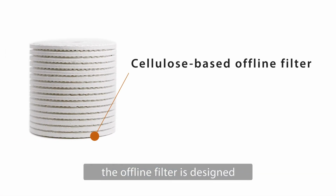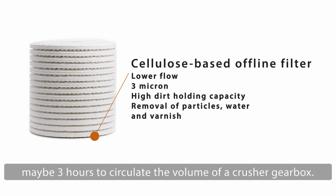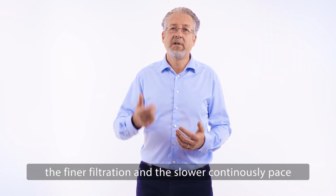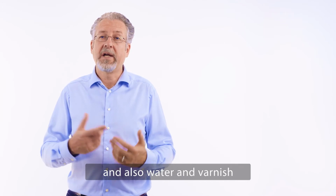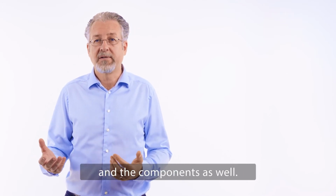The offline filter is designed to slowly circulate the oil volume over the filter, maybe 3 hours to circulate the volume of a crusher gearbox. The finer filtration and the slower continuous pace means that you'll be able to take out more contamination and also water and varnish, which will prolong the life of the oil and the components as well.